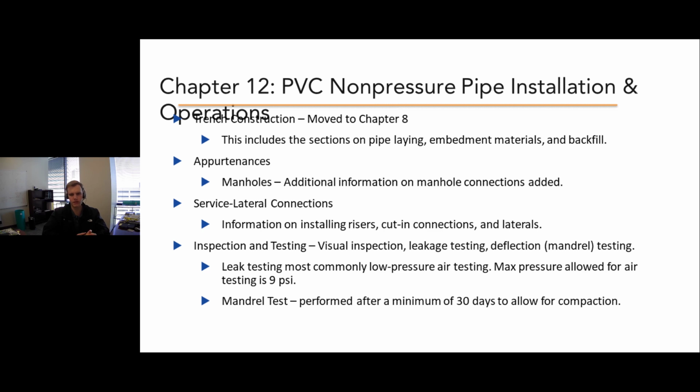Mandrel tests, those are the deflection testing mentioned earlier, and generally those are performed after a minimum of 30 days to allow for deflection to have occurred.